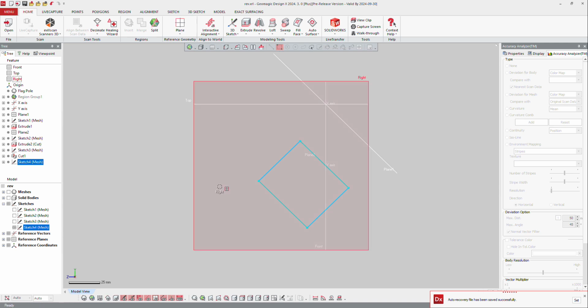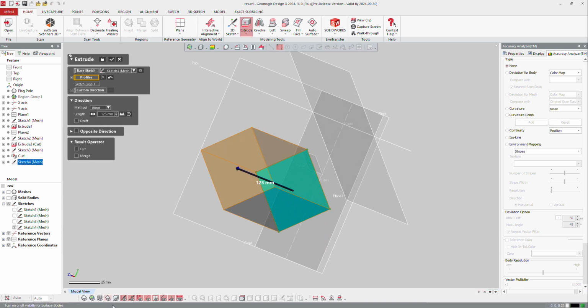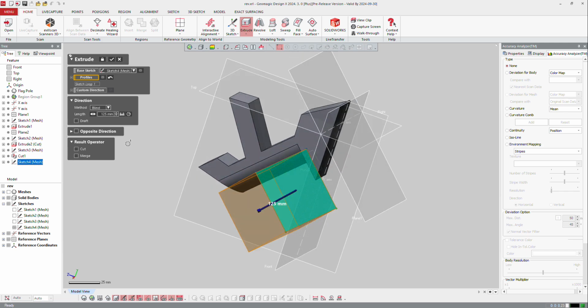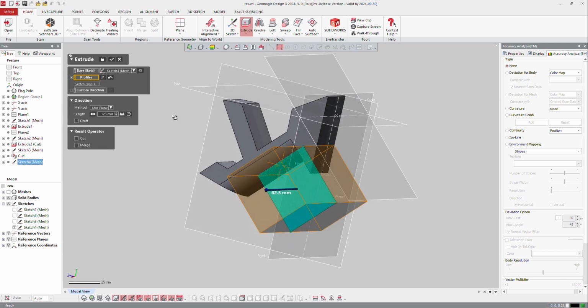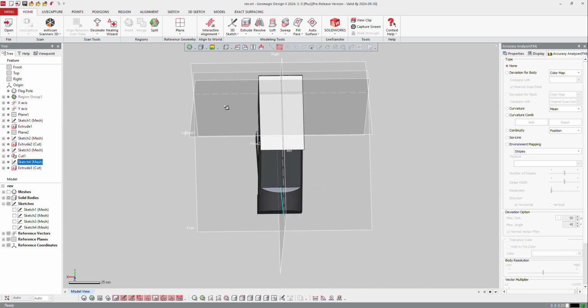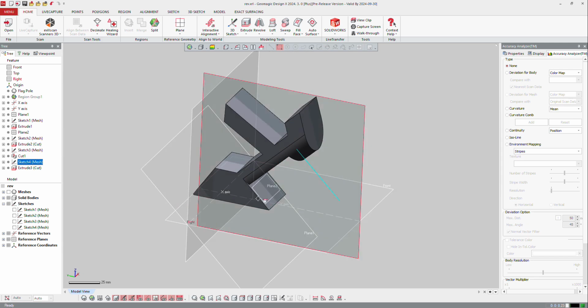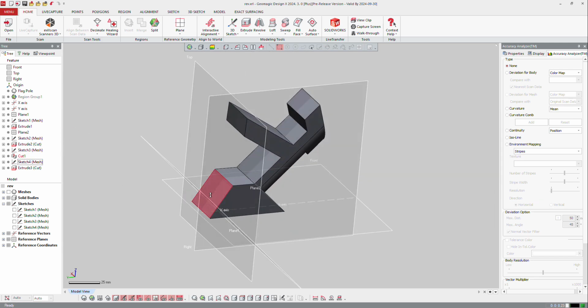From that, I will just extrude, display my solid body and extrude it mid-plane just to cut the model. So I do not need to make it too big, so maybe 60 millimeters should be enough, and cut. And okay. So now you get a nice opening here, and I can continue the part by just making maybe this area.